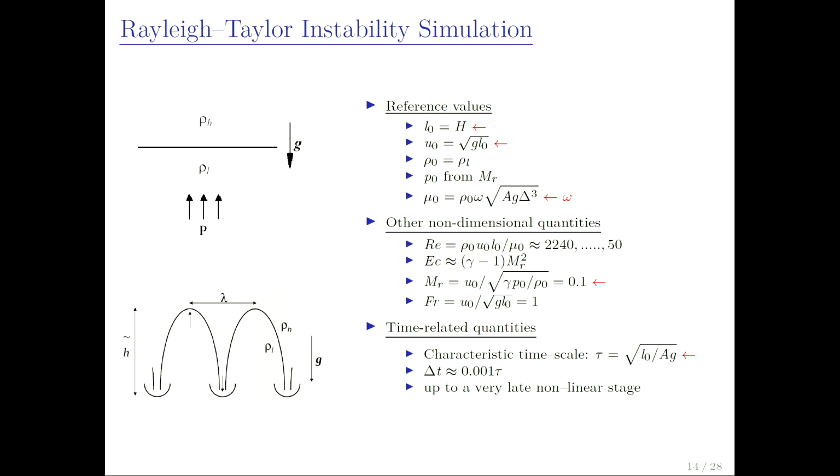Initially, you have to provide a kinematic viscosity to the method, or algorithm, or simulation. It depends on the Atwood number and your resolution, of course, and it is scaled by this term. You have to choose this term correctly to obtain physically reasonable results. It takes some time to determine this scaling factor.